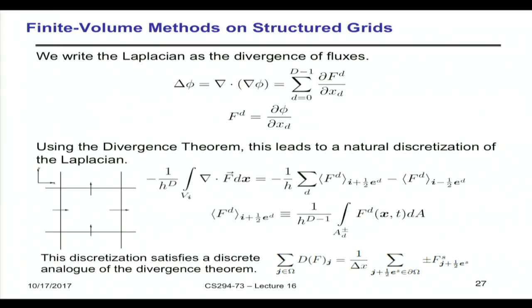So I don't think you've had any discussion of finite volume methods, have you? None at all. Okay. So finite volume methods are quirky. Instead of a node-based concept, you end up with the thought that this is a cell average. And if any of you have done any kind of physics course, you know about conservation within a control volume. So for example, for the Poisson equation, you use the divergence theorem to turn this into a difference of gradients across all of these faces. Right? So the divergence of a gradient is your Laplacian.